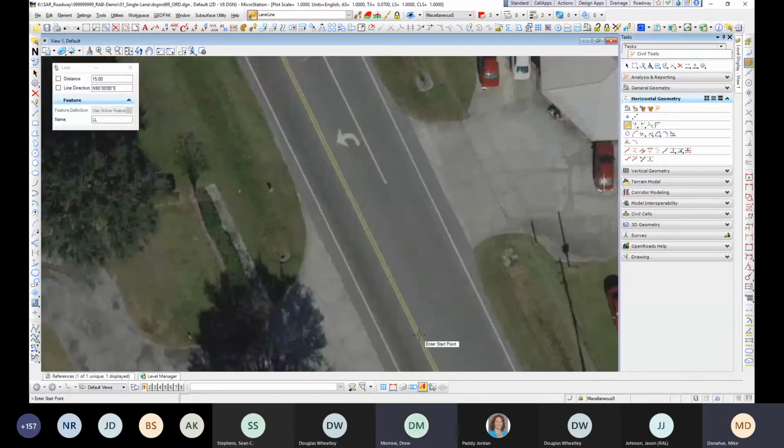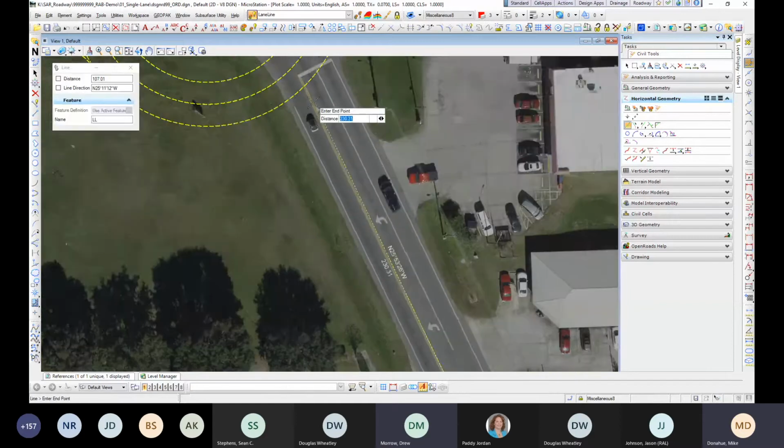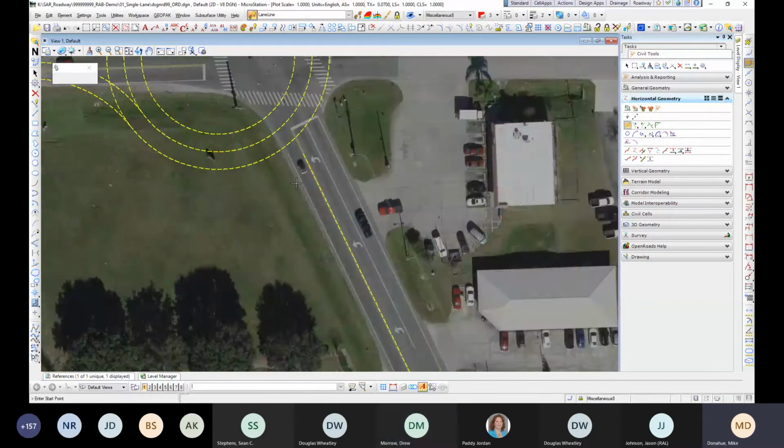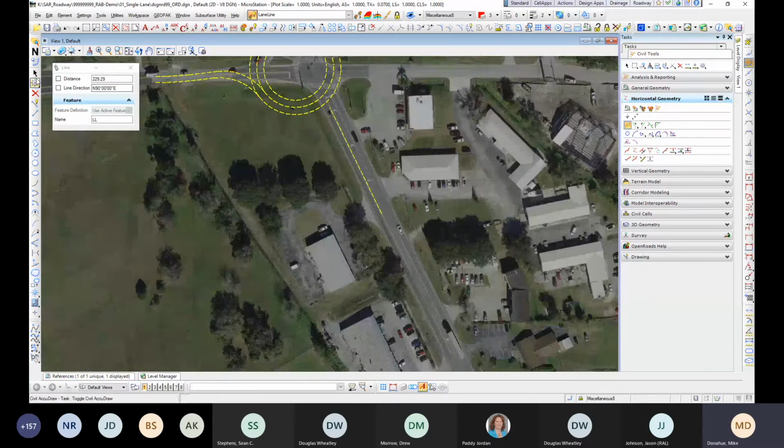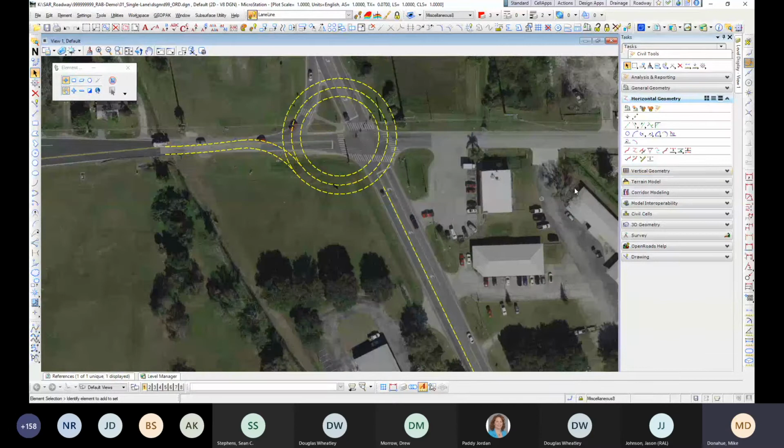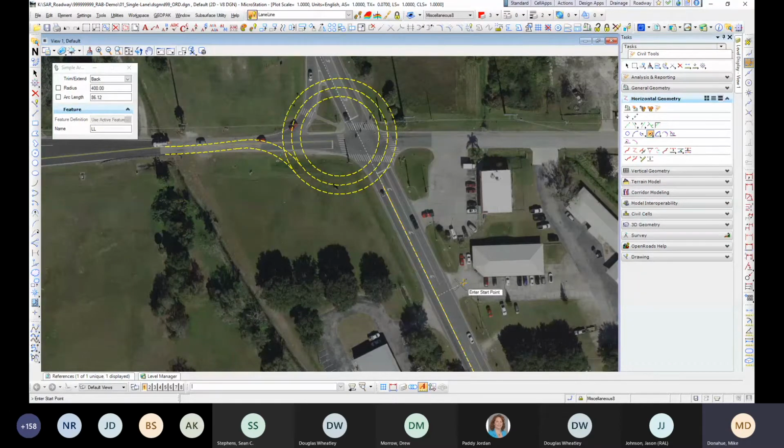And I'm going to add my 2-lane entry. I'm going to make the assumption here. And I'll just hold that existing geometry initially. Scoot this back a little. This is going to be a little higher speed, I think. So I'll start my radius on this element. See if I can avoid this driveway. Let's see what that does.